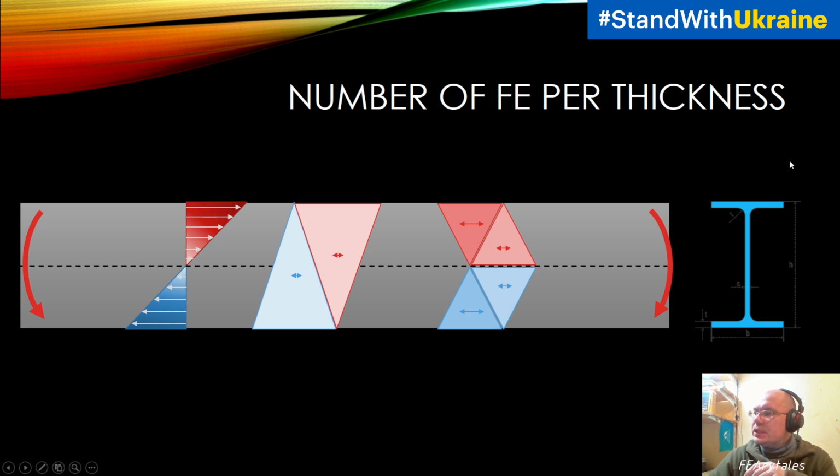But this I-beam, C-beam, O-beam, and so on, came into our task as solid geometry, for which they create a solid mesh. And that's a very different situation. So for these I-beams, for all other beams, you don't need 2 elements per thickness. But we need to understand that sometimes, even for a beam section, we need 2 elements and even more. It's for local stiffness and local stress behavior description.